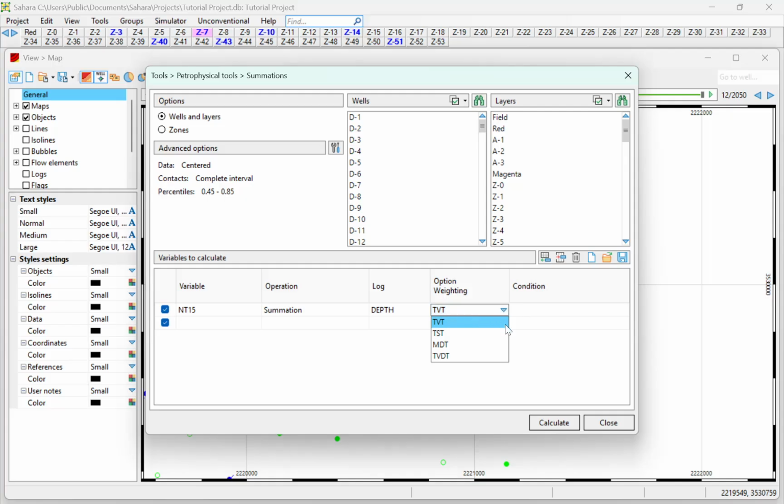Here you can review more of these calculations in more detail in the manual guide as well, but this is going to be important for wells that have surveys, horizontal wells or directional wells, because the definition for the net thickness might vary depending on the inclination and the azimuth, and the relationship between those and the geological angle of the layer compared to the horizontal line. So in that case, you can review in more detail what the different options mean in the user guide